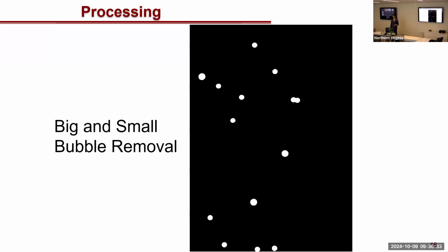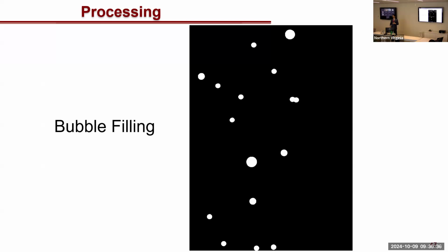So the big bubbles that were screened out here were from bubbles shearing off of the air pocket on the side of the bubble injector. There wasn't a perfect seal within the flange and the test section, so there were some air pockets that formed, and these very large bubbles most of the time came from bubbles shearing off of that. That's something that should be improved in future work. Did you observe that, or is that speculation? It was observed.